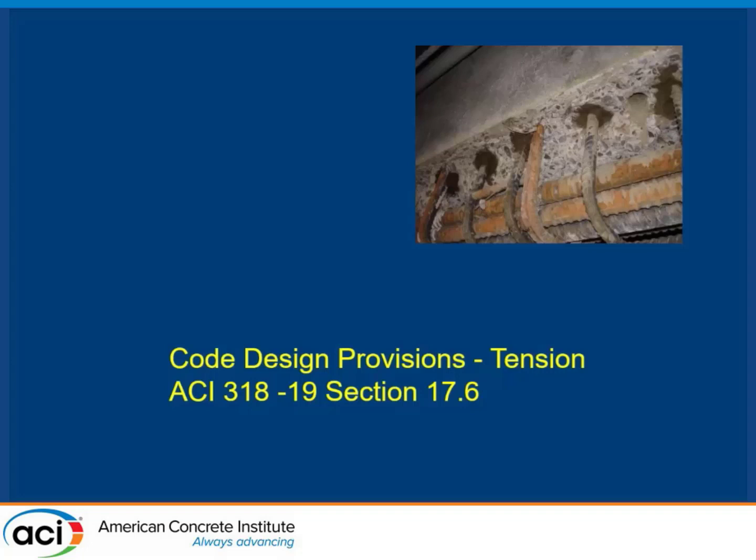Well, the Big Dig, and we're all moving ahead here, but that's all right. So the question was, it seems like, and I've heard it go both ways, it takes more time and effort to use one particular mechanical anchor, or it takes more time and effort to use an epoxy anchor. I think contractors prefer epoxy anchors for the most part, but now with the requirement of being certified and stuff like that, that's kind of taken some of the fun out of it. The mechanical anchors are real quick to use, but like you said, some of the less expensive anchors out there might not be all that great in cracks.